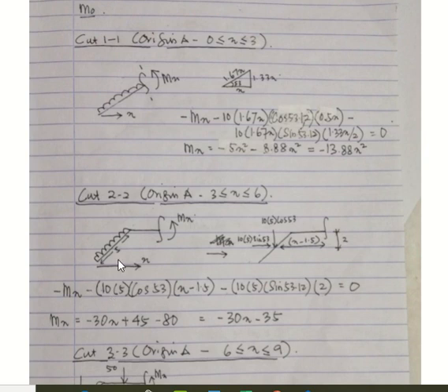And again, we consider incline UDL for member AB. But now, you're cutting not at the UDL like cutting number 1. Now, you're cutting on the member AB. So, you must consider the whole UDL on member AB.